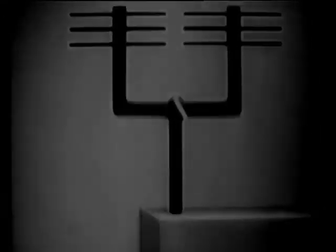The antenna is designed so it can receive echoes alternately, first from the right lobe, then from the left. Notice, however, that each lobe is on long enough for a pulse to be sent out and its echo to return from maximum range before the next pulse is sent out through the other lobe. To handle the echoes from each lobe efficiently, to keep them from being mixed up, a special receiver circuit is used which acts like a gate. This gate allows signals from the left lobe to pass through, and then those from the right lobe. The signals go down through the receiver alternately and onto the indicator.